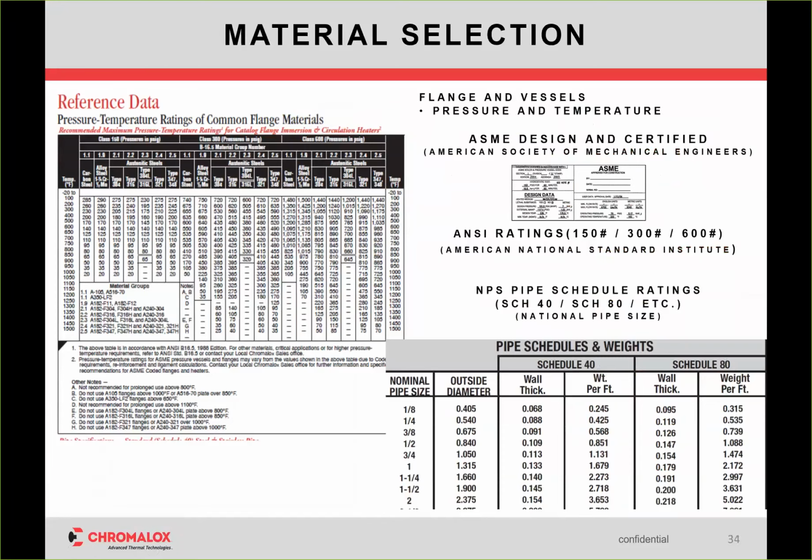Flanges. I bring this up for consideration because we standardize on a certain type of flange. Now, ANSI flanges, American National Standards Institute, set size, bolt diameter, thickness, and type. And these are all just standards that go on the mechanical end, the tank connection, the nozzle, the flange, and they're all easy to follow. We offer all. We don't make flanges. We obviously buy, drill, and put our elements in them.